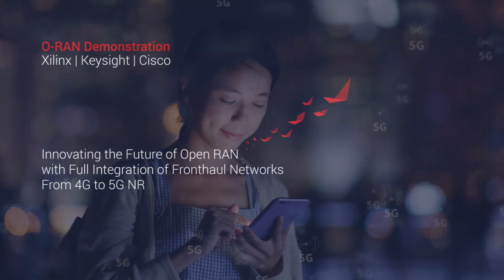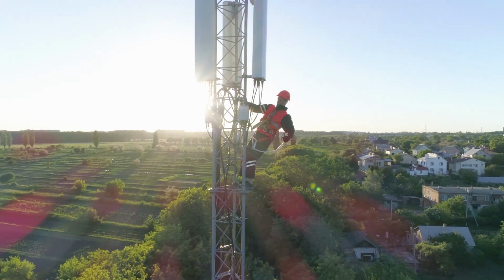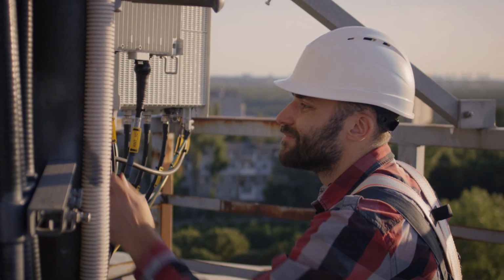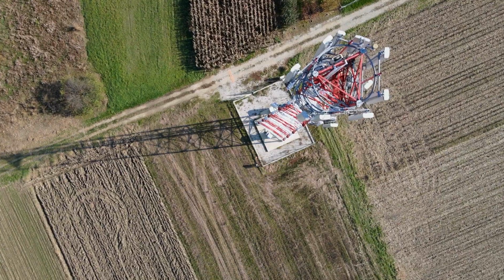Mobile radio access networks are seeing a paradigm shift from proprietary interfaces to open interfaces. The radio base station and the radio are typically connected through a proprietary interface called CPRI. With the advent of Open RAN, this interface becomes open, standardized, and can run over Ethernet. This really allows mobile network operators to mix and match equipment from different vendors in their network.